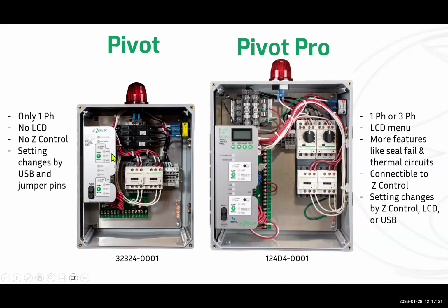You can change settings. There are so many settings within these control panels that are customizable. We're going to be talking through a lot of that, but there are multiple ways of changing them, either through a USB device or through some jumper pins on the back of the circuit board that you can pull that will manipulate some of those behaviors.